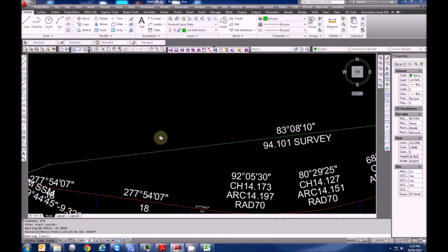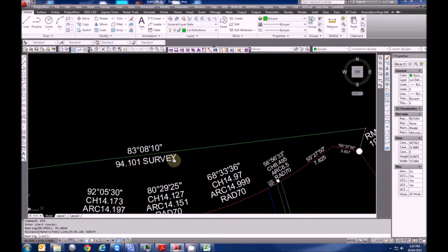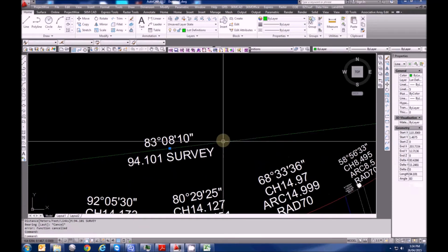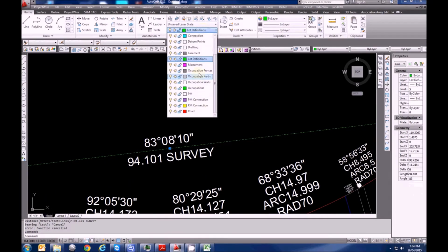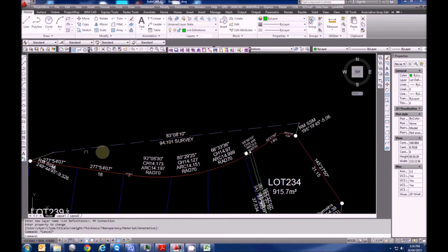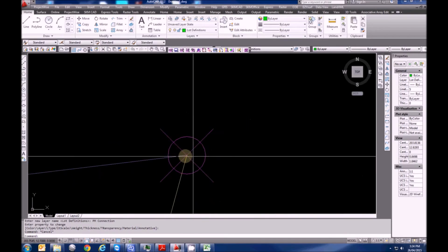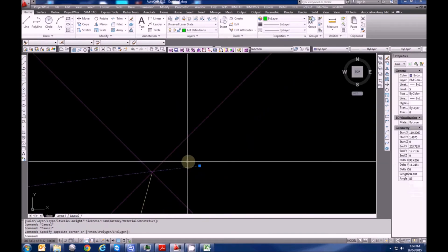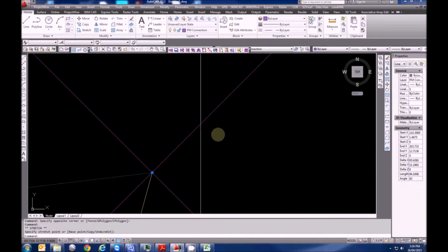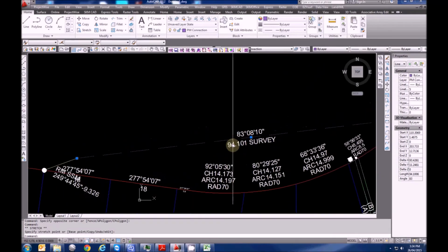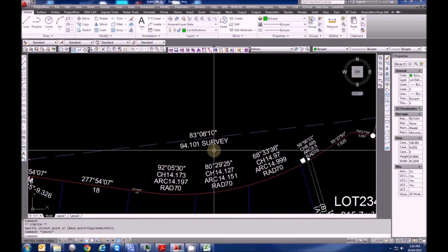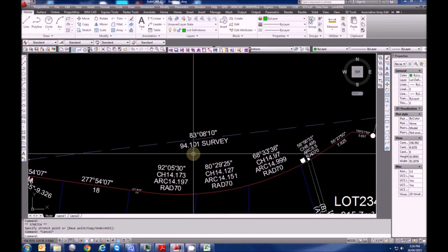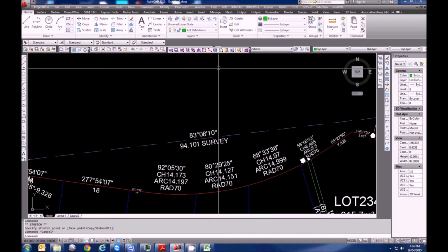And what that does is that creates a field note on the line, and you can see we're also in a layer of definition, so I'm just going to pick that up and put that in PM connection, and it becomes that nice purple colour. You probably also have a tiny little misclose here, so we just pick up the end of that line and pop it in there. Okay, so we've got our survey distance between the two lines. We also need to apply a scale factor to that. What Andrew's scale factor is for this job.